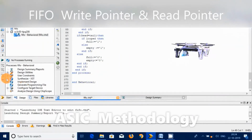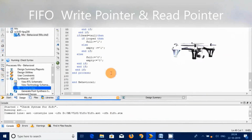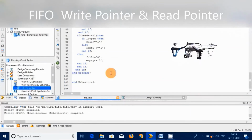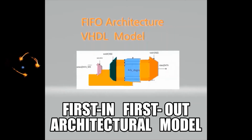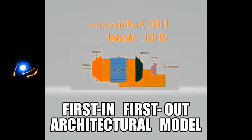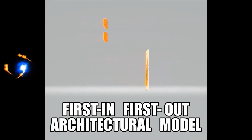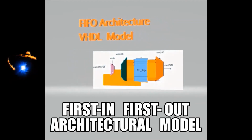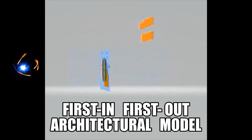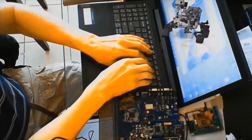In the dual port RAM model segment of the FIFO, it has a write counter to address the write side of the RAM and a read counter to address the read side of the RAM, and the control logic updates the write counter at each write of data into RAM, and the read counter every time data is read from RAM.